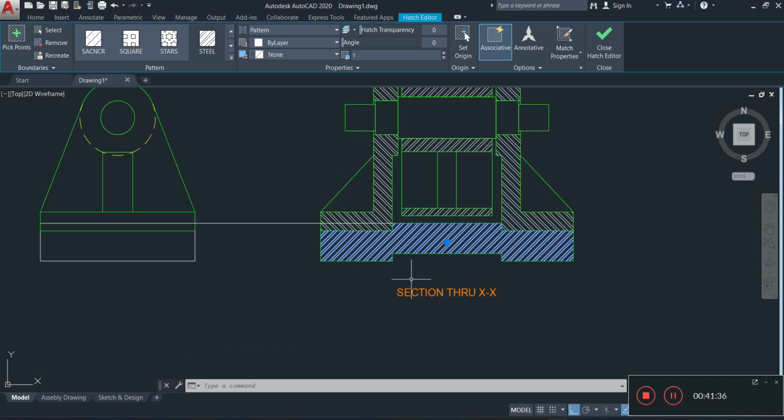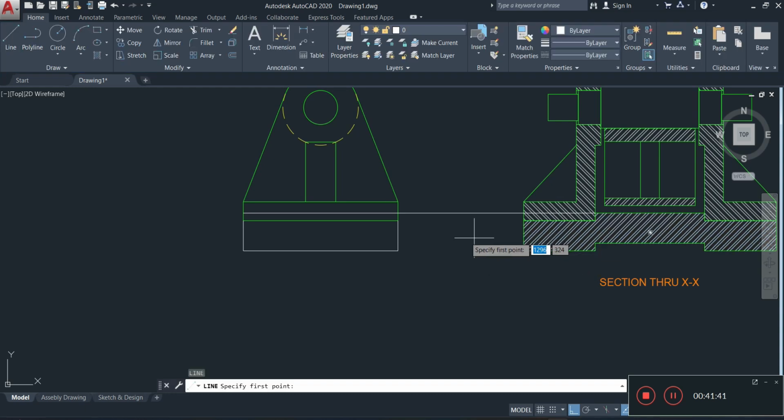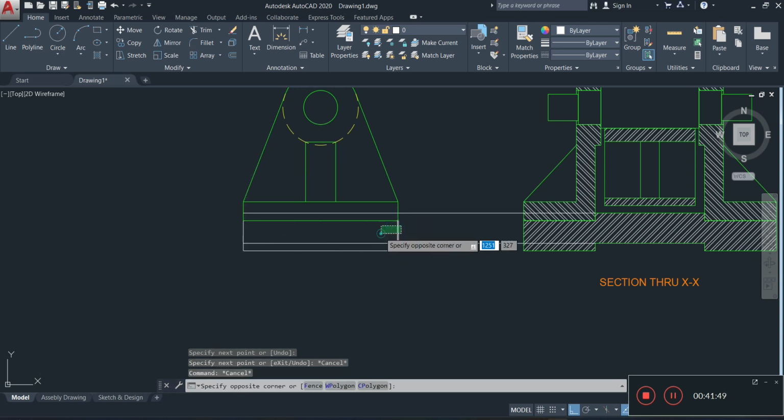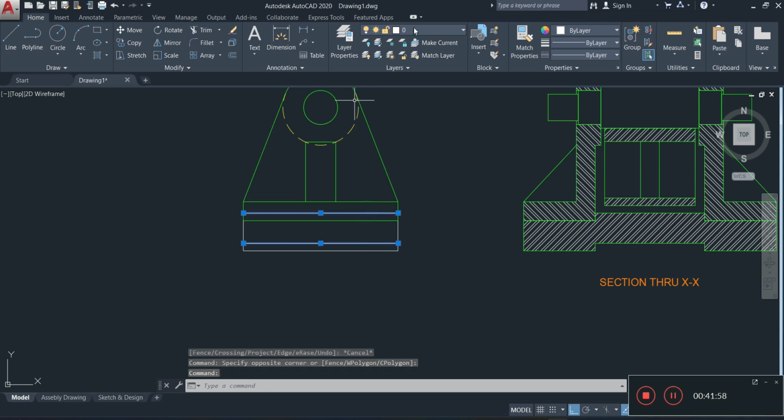So that's the portion we're capturing. You know the reason why we use hidden details already: these will be hidden detail. We know that they're there, but we know that they're being blocked. So we're going to represent that using hidden detail lines. Let's add these to that layer, the hidden detail layer.